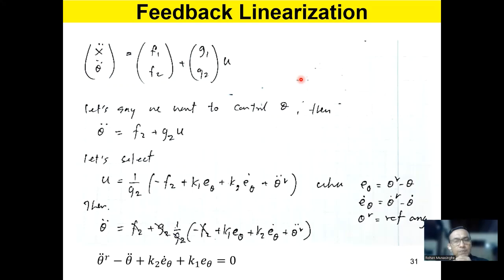Now, let's say we want to stabilize the plant. Let's not worry about the positioning of the cart, just stabilizing the pole vertically. So that is the second equation over here: theta double dot equals F2 plus G2 times U. So we'll write down that equation. For the moment, I disregard cart position.